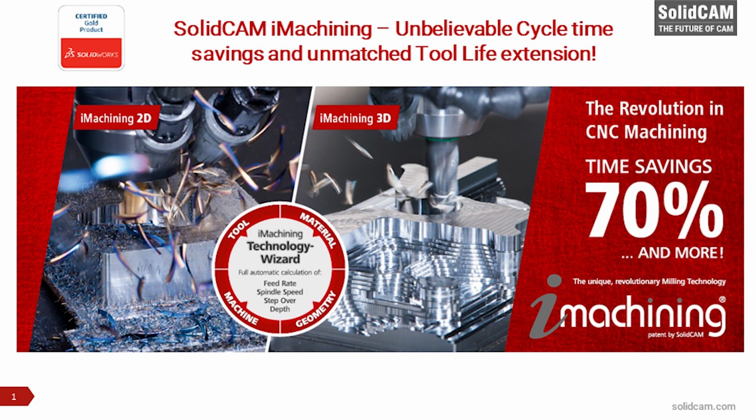I tend to also use it to minimize spindle load. If I program something for level 8 being 40% or 50% spindle load, and it turns out when I get out on the machine that it's running a little higher, like 65%, a lot of times I'll just go back in and drop the level slider down one notch and repost the code and put it on the machine, and we're off and running.